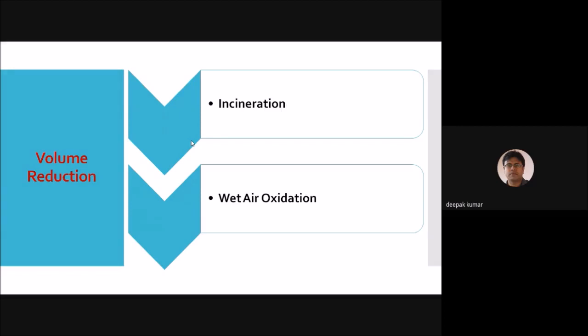Raw primary sludge with about 70% volatile solids contains about 7,800 BTU per pound of dry solids, and once combustion is started, it will burn without supplementary fuel. In fact, an excess of heat is usually available. So in this way, the incineration process reduces the volume.